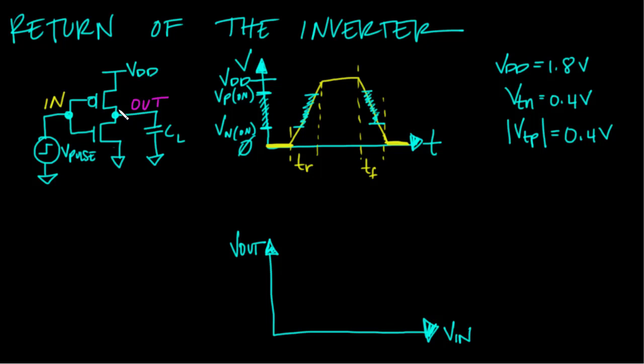So this is an intrinsic property. What we can do to make it so that the NMOS device sinks as much current as the PMOS device sources is we make the PMOS device a little bit bigger to account for the fact that the mobility of the holes is less than the mobility of the electrons. Ideally, as much current as this PMOS device could source, this NMOS device could sink. This node would be at VDD over 2. It'd be halfway between because this would be sourcing, this would be sinking.